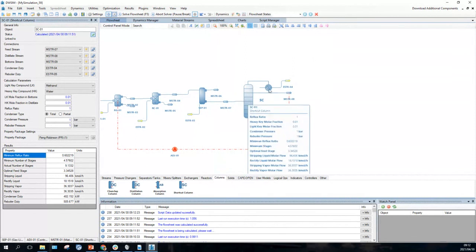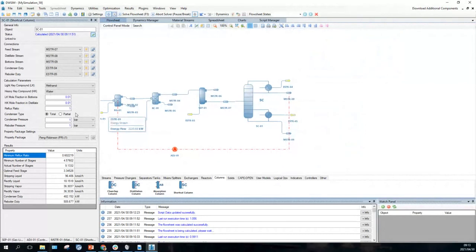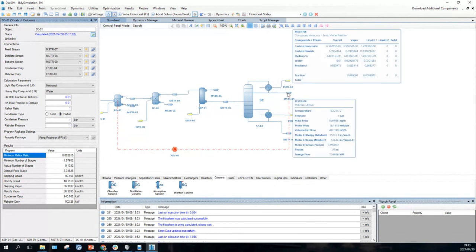And we went in here, and by taking off the CO2, or the non-condensable gases, let's go back. This is minus 55 degrees. If we make it a partial condenser, we could take off the CO2 as a gas, and then we don't have to cool this condenser down as low as minus 55 degrees C. Now we can use cooling water, 62 degrees C is higher than 40 degrees C. Normally we'd be limited to 40 degrees C at the condenser.